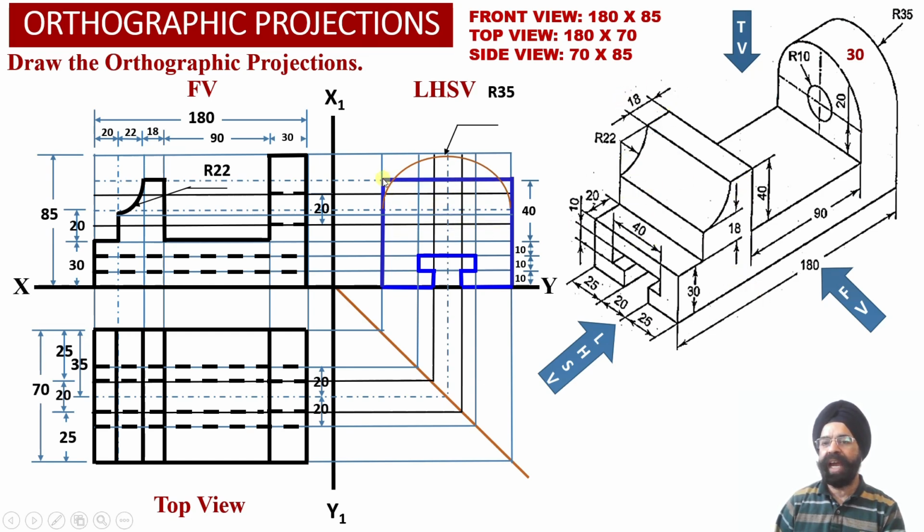And next we know that because we have got a flat surface over here, we can draw a flat horizontal projector line so that a rectangular projection we will be able to witness from the left hand side element number 2 surface over here, which is having total height of 70 millimeter from the ground.